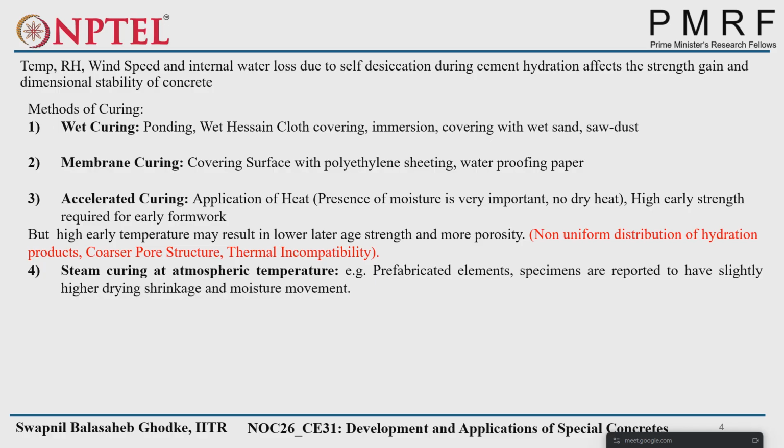Steam curing at atmospheric temperature. Has anyone seen this type of steam curing in the industry? Most of the prefabricated elements use this type of curing. Railway sleepers, right. Bridge girders, if they want to go for prefabricated elements, also go for steam curing at atmospheric temperature. But what happens?